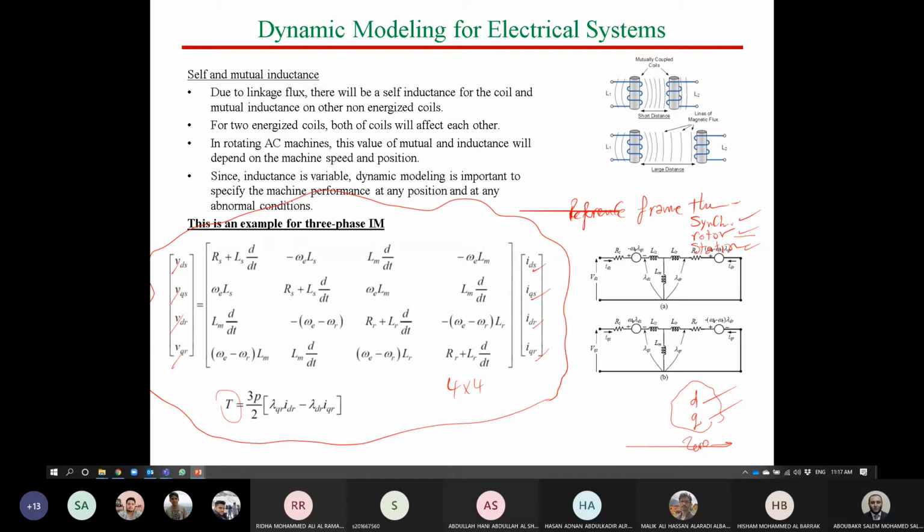Let me now give you an example. I have a motor with a rated speed of, for instance, 1700 RPM, and the synchronous speed is 1800. And you need to control this motor in an electric vehicle. So in an electric vehicle, is the reference speed going to be constant or variable, guys? Reference speed means the speed command that you are going to give to the motor in order to operate your car. Is it going to be fixed or variable? Fixed. So you are going to move with the car at a fixed speed? No, it should be variable.